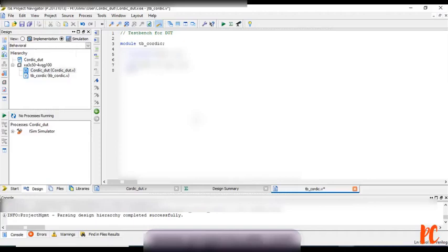Followed by reg which is 31 again down to 0, for the angle, again reg for the clock signal, and again reg, this time taking sine with respect to 63 down to 0, for iterations, so I am considering it to be I. Now wire width minus 1 down to 0, followed by cos underscore out and sine underscore out.